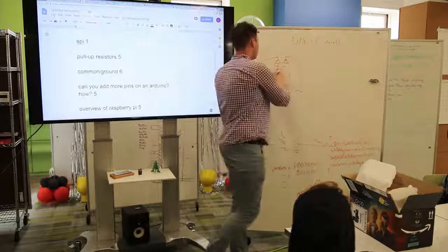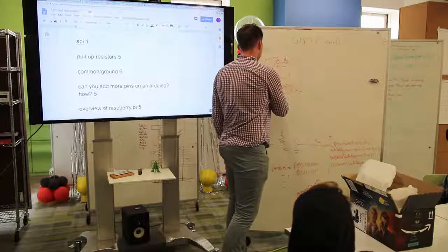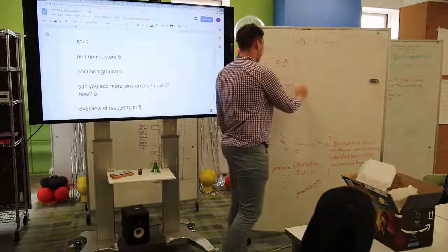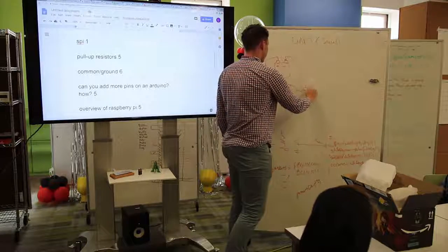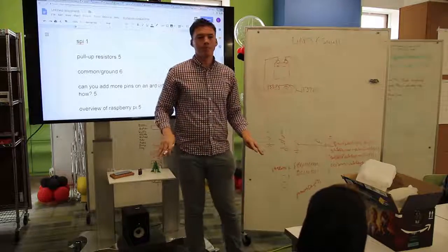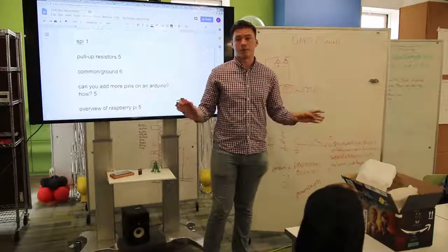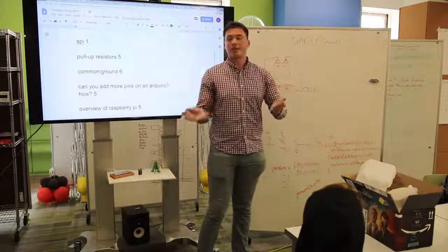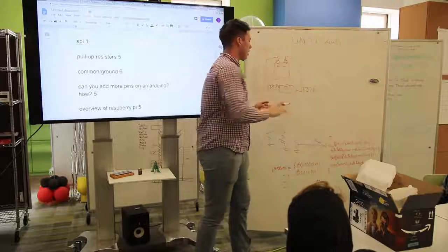If I wanted to, I could say that actually this is 1,337 volts, and then this is 1,328 volts. And now on this side, that would be totally valid. There'd be nothing wrong about that. But electrical engineers don't do that because we don't hate ourselves that much. Usually what we do is we pick a node that makes sense and call it 0 volts. And that's ground.